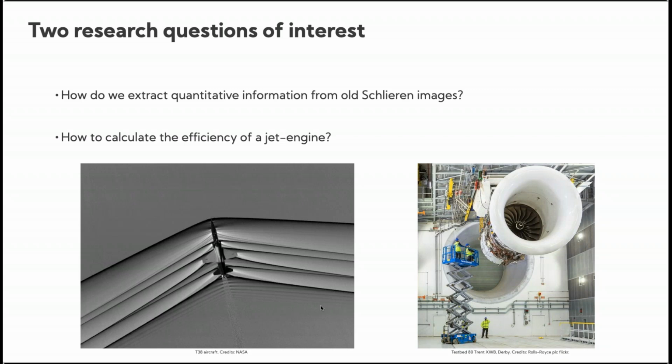You simply determine how much fuel you're putting in, how much thrust comes out, but it's the breakdown of that propulsive efficiency multiplied by thermal efficiency into its different components that is much more challenging to determine. So for instance, if I wanted to ascertain what the efficiency of only the high pressure compressor was, that problem is a lot harder compared to understanding the efficiency of the entire power plant. And I'll explain why as we continue.